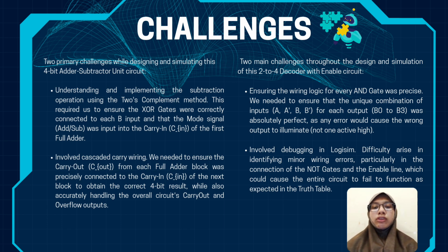We needed to ensure the wiring logic for every AND gate was precise. We needed to ensure that the unique combination of inputs for each output was absolutely perfect, as any error would cause the wrong output to illuminate. This circuit involved debugging in Logisim. Difficulty arises in identifying minor wiring errors, particularly in the connection of the NOT gates and the enable line, which could cause the entire circuit to fail to function as expected in the truth table.